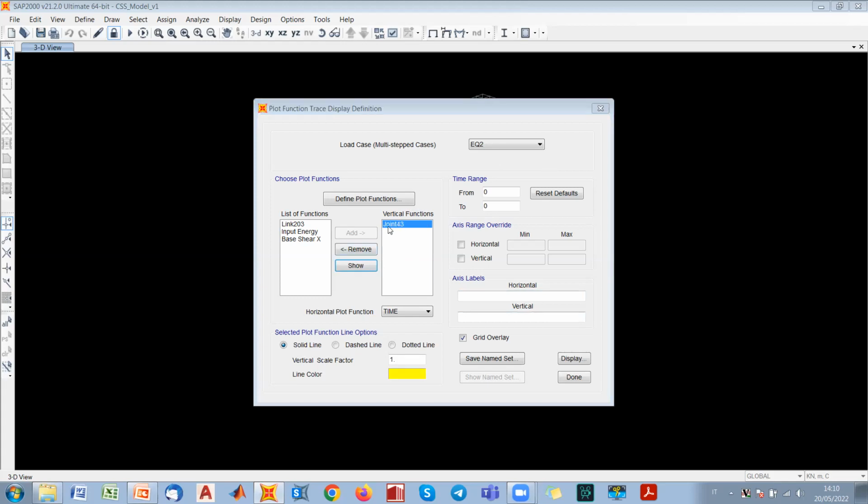And if you remember, we considered this point, which was a corner point of the reinforced concrete plate. This was just because we can choose whatever point at the same location for the isolation system, since we are not expecting to find a significant torsional behavior for the isolation systems. In this case it is even more true because this is the curved surface slider isolation system. This particular typology of devices allows a very negligible torsional motion of the overall system. But we will get exactly the same behavior also for rubber bearings and lead rubber bearings.